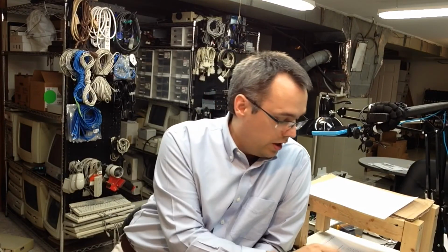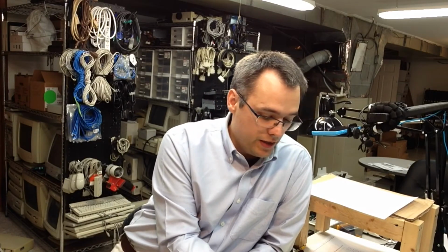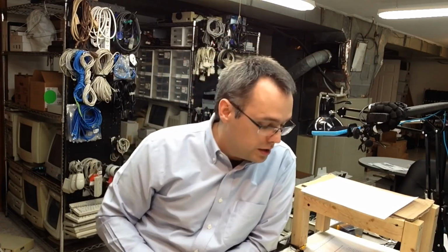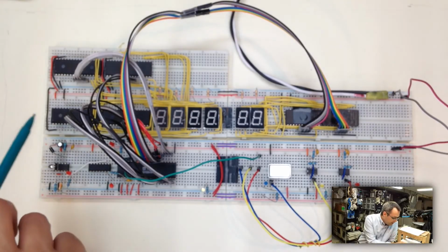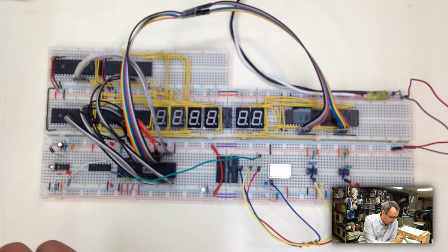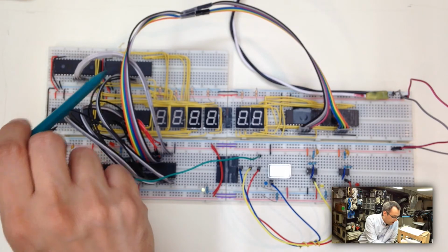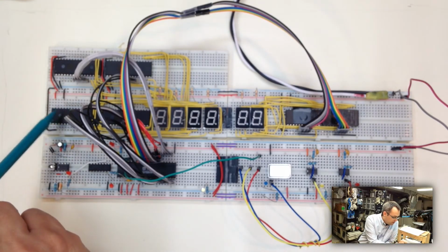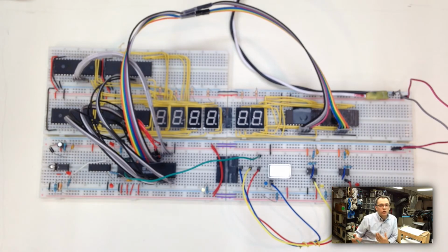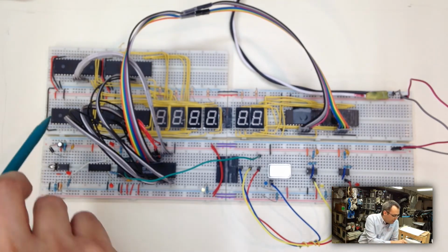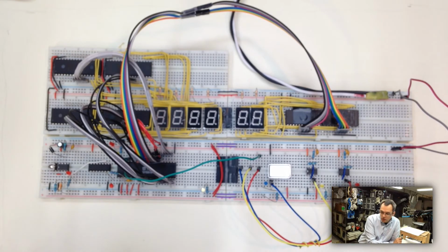Other things that I wanted to talk about, I had some questions in the comments from the previous video about some details about how I made the hexadecimal address decoder work. I'll go into a little bit more detail of that right now since I got everybody's attention. The hexadecimal converter works basically by having a truth table in these ROMs. I got these 1 megabit ROMs, or 128 kilobyte ROMs, off of Mouser for about, gosh, what did it cost me? They were actually about $1.97 a piece.